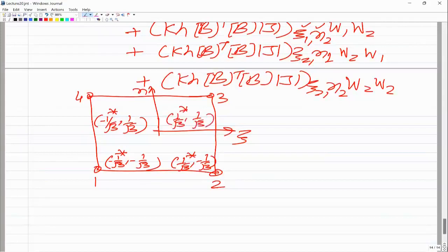So these are the four Gauss points, G1, G2, G3, G4. These are used for the numerical integration of the element level governing equations in the natural coordinate formulation.